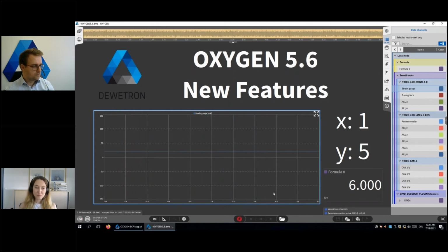However, now it is possible that I force a manual trigger. So arm my trigger, and now if I stay on the button, I can see manual trigger. So I'm not pressing my space bar, but I can press manual trigger and the waveform recording starts anyway. So I don't have to wait for an event. I can just force a manual trigger if needed.